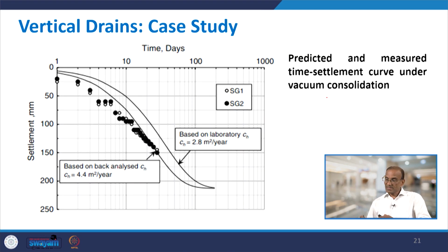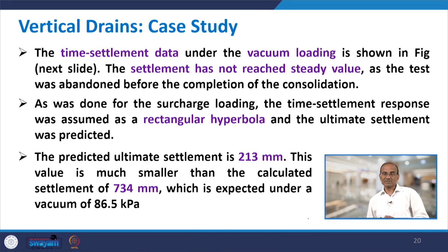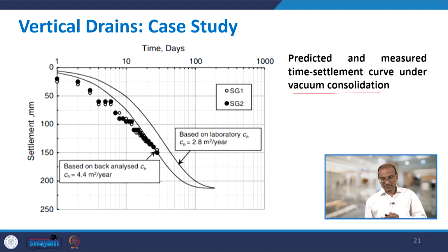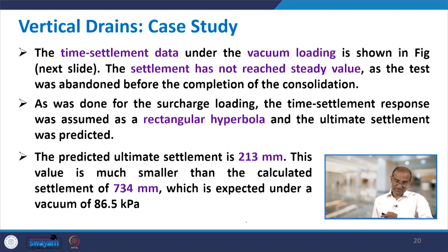Similarly, the data has been collected for vacuum consolidation also, and the time settlement data under the vacuum loading is also shown in this figure. The settlement has not reached a steady value, as was the case earlier where it becomes flat. It has just started reaching there, and even the settlement was large, more than 200 mm compared to the last case. This is based on the vacuum consolidation.